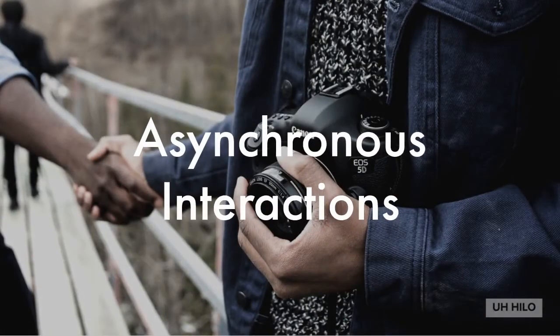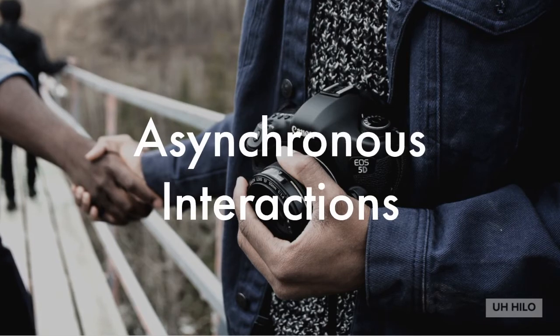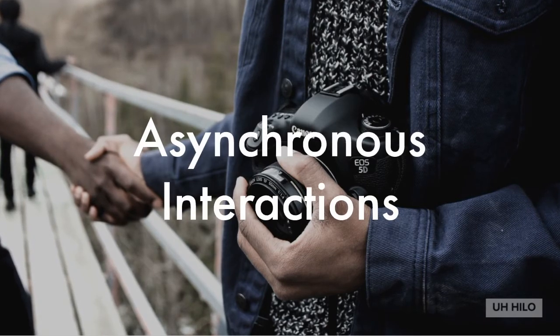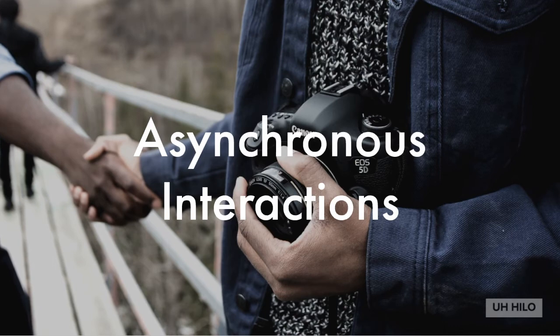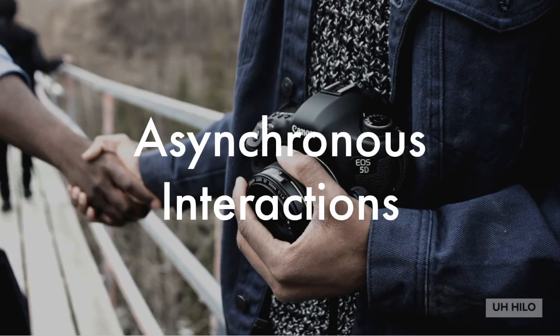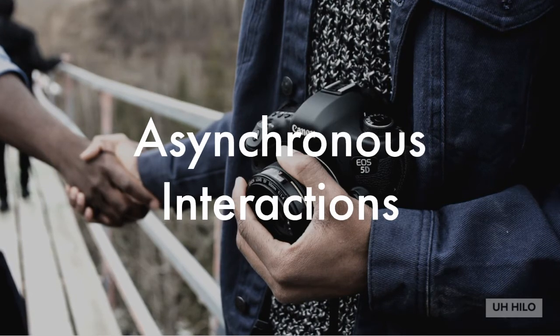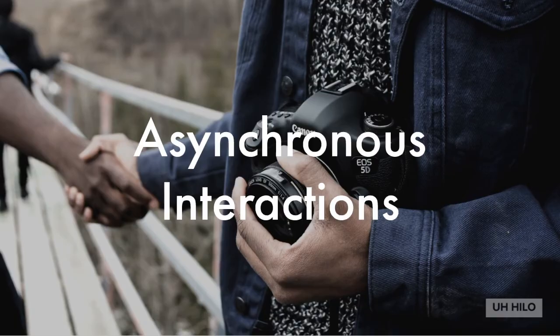An asynchronous circuit has one or more state variable changes that occur without being directly synchronized by the special clock input. Instead, an asynchronous circuit may change state in response to any of its inputs. The interactions between synchronous and asynchronous circuits can be strange, to say the least. Interactions between two synchronous circuits having clocks that are unrelated to each other also get a bit weird.